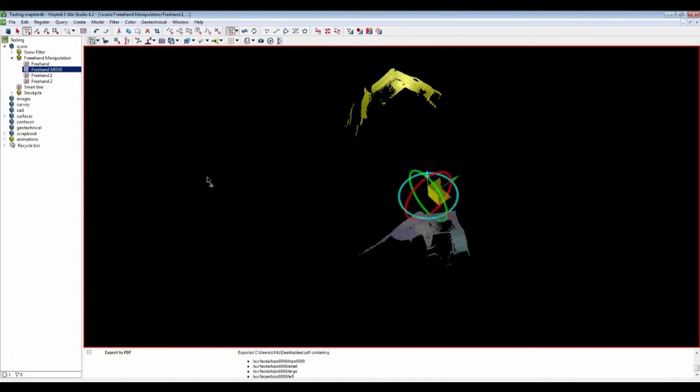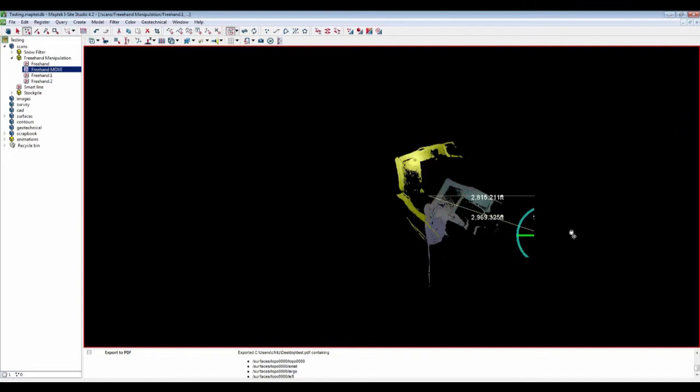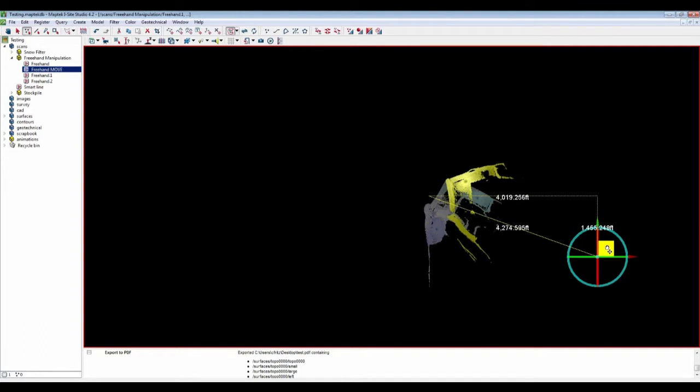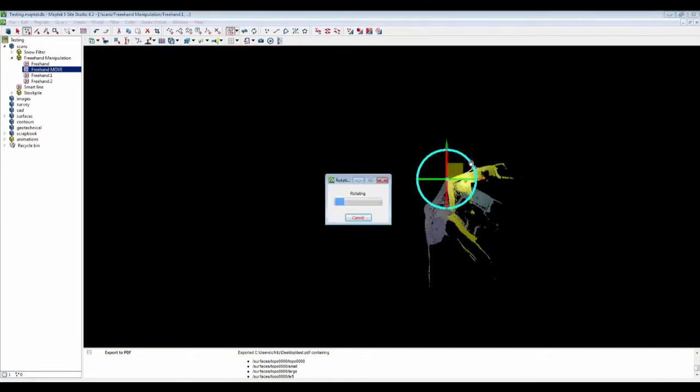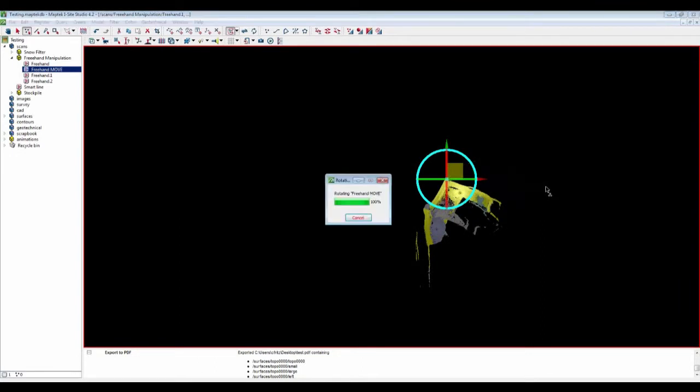So I'm going to show you what this process looks like. What I'm going to do is select this translate, and I'm going to move it to where I think I am close on that corner. And then I'm going to use the hotkey C for moving my center of rotation. Then, by grabbing that rotate bar, I can move it. Now at this point, I never would have guessed 39 degrees. Maybe some of you are that good, but this way you're not just putting in numbers, clicking it, and seeing how far it moves. You can just line it up. Just wait till it looks good. All right, that looks relatively close.